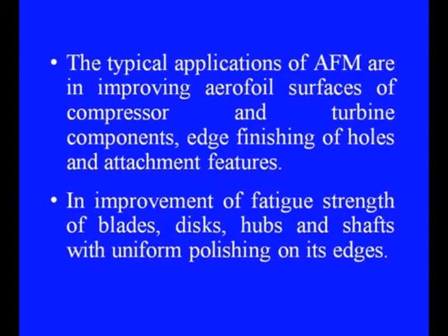improvement of fatigue strength of blades, discs, hubs and shafts with uniform polishing on their edges, the adjustment of airflow resistance in blades, vanes, combustion liners, nozzles and diffusers, finishing of fuel spray nozzles, fuel control bodies and bearing components, reworking the components to remove coke and carbon deposits and to improve surface integrity,